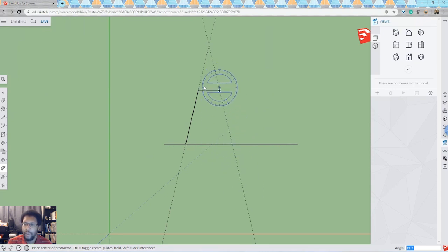It's key to note here that before, if we looked at the angle that it was before, it was technically minus 13.7, meaning that it was shifted towards the left, and when we put it over here, we just typed in 13.7. That means it's a positive angle, so it was sweeping counterclockwise, moving from left to right. Just be careful of that. If you type in the number and it makes it perfectly parallel, like an intersect like this, just change it, make it either positive or negative, and it'll fix things like that.